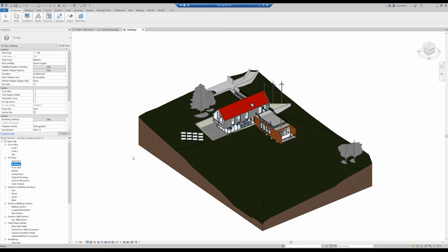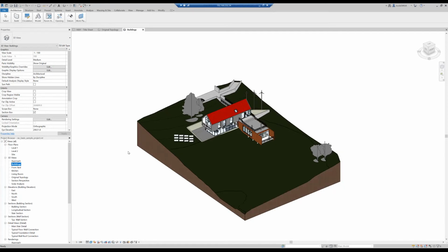The first thing is the topology. Now, we mentioned earlier that we wanted to extend the default or the current original topology because at the moment it's not sufficient for CFD simulation. If we put a wind tunnel around this, the edges of the topology would influence the results. Really, we just need this to be extended past any boundary that is held by the wind tunnel. Which means in an ideal world we'd want to grab this face and move it out, say a couple of 100 meters, maybe a kilometer.